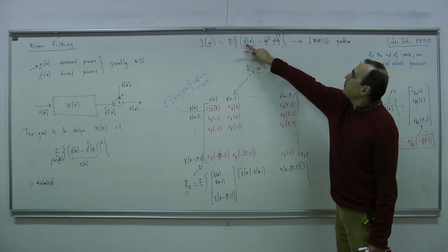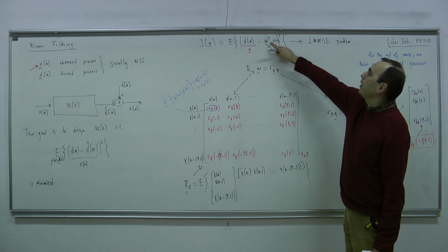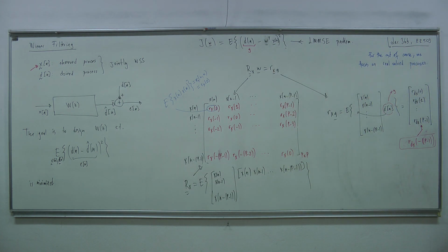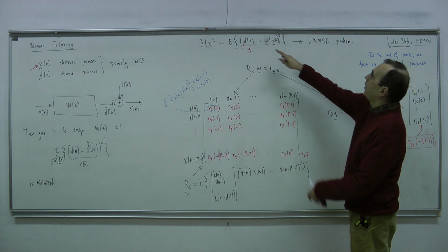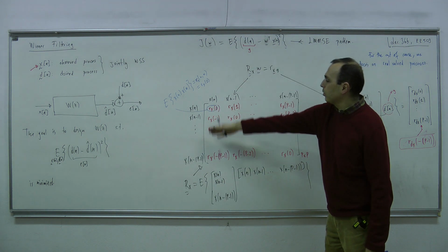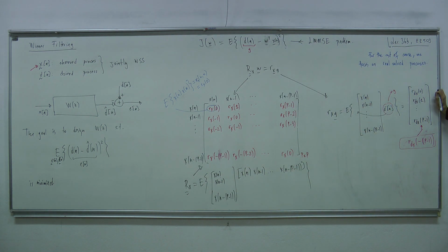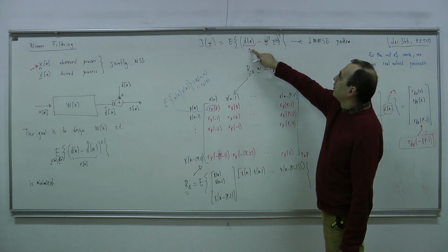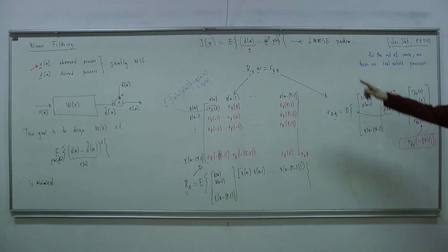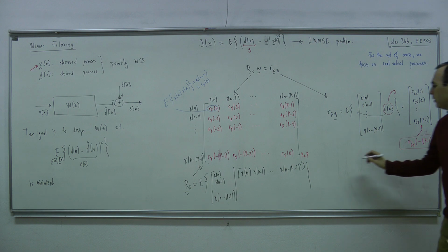If I want to estimate d[n+1] from the x[n+1] vector, I get exactly the same optimal coefficients. Because if I shift this by one sample to the right or to the left, this correlation matrix and this matrix do not depend on that. So instead of defining y as d[n], if I define it as d[n+1], I get exactly the same equation system.